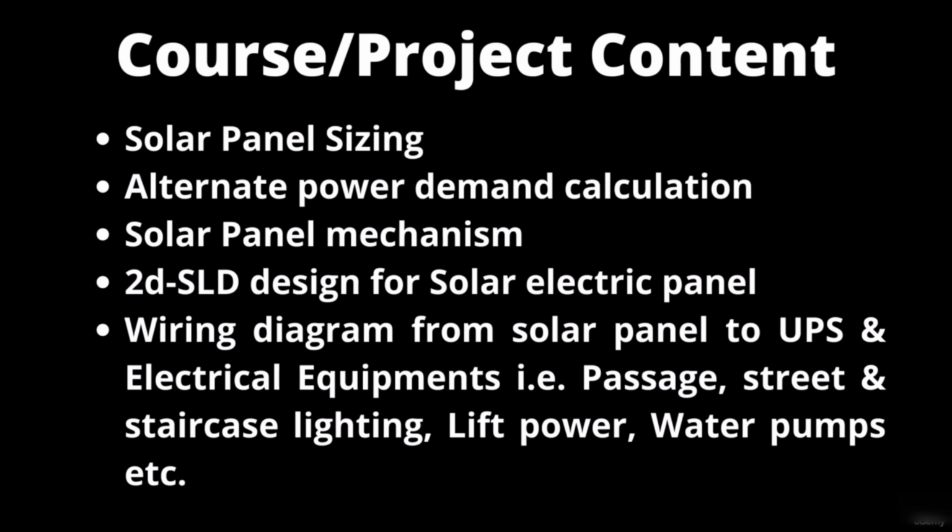This project contains solar panel sizing, alternate power demand calculation and solar panel mechanism, a 2D or SLD diagram for the solar electric panel, and the last one is the wiring diagram for solar panel to UPS or the inverter and the electrical equipment, that is passage, street and staircase lighting, lift power and water pumps, etc.